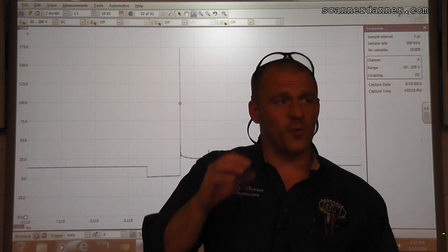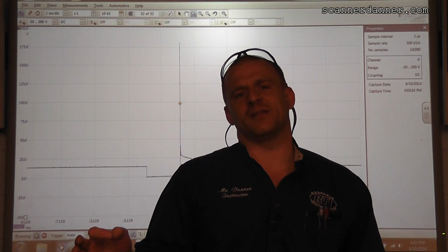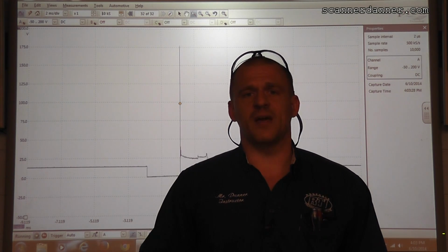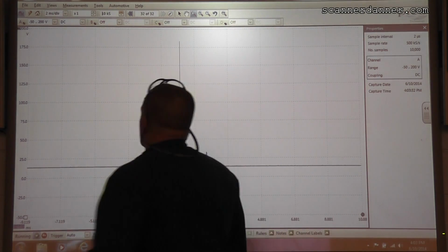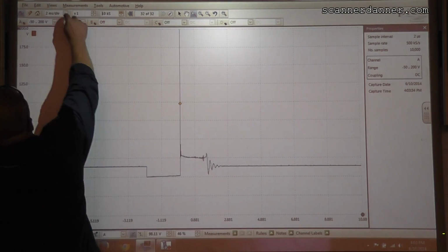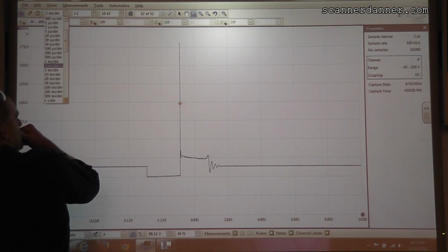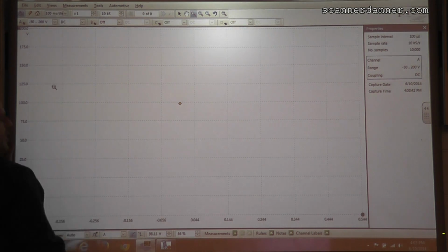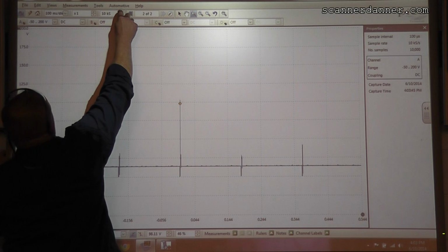I want to see both. I want to see detail, repetition. So I want long time bases for that particular scenario. Long time base, I need to raise my sample rate for that. So I'm going to show you that on this car. I want to set this to, oh, I don't know. Let's go 100 milliseconds per division. That's where we were. Let's start with that.